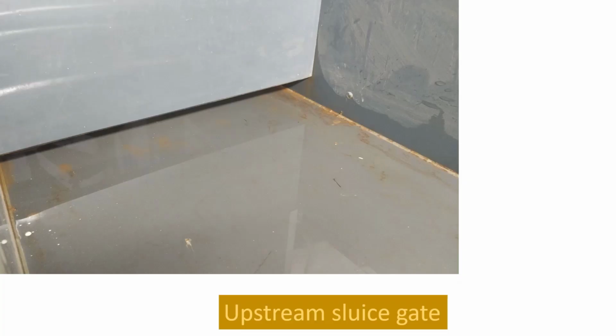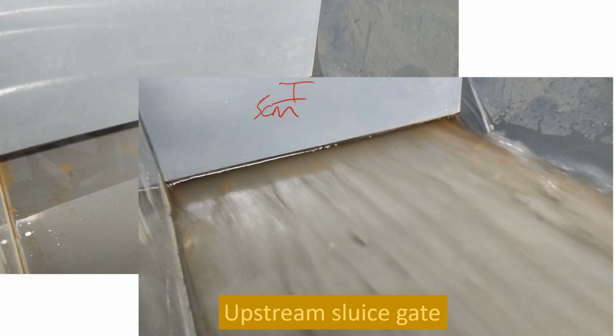How do we cause that hydraulic jump? Because, well, I've said already, we've got an upstream sluice gate that gets the depth low. Now this is about 5 centimeters. You don't actually need to measure it for the lab. You need to measure the depth of the water, but that forces it down low. That's it flowing with some water in it. Actually it goes a bit lower than 5 centimeters, so we get about 3 centimeters.